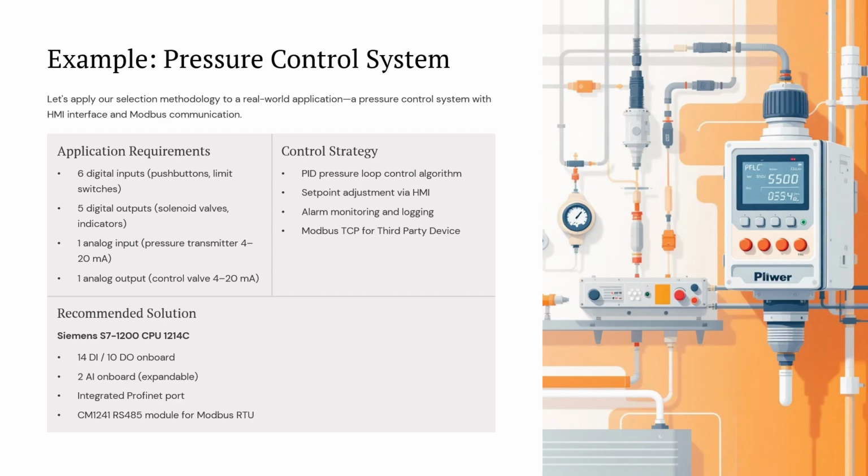Based on the application, a good choice will be Siemens S7 1200 CPU 1214C and one 4 analog input and 2 analog output card with the communication module.